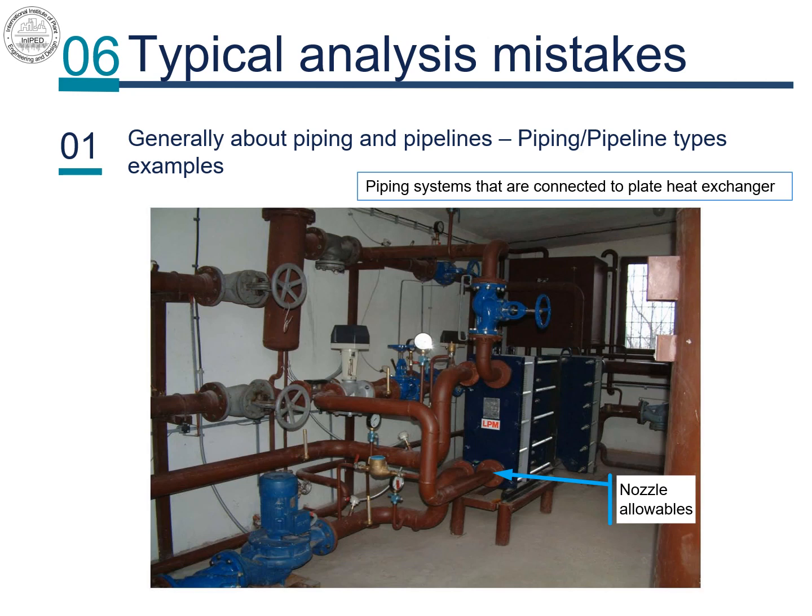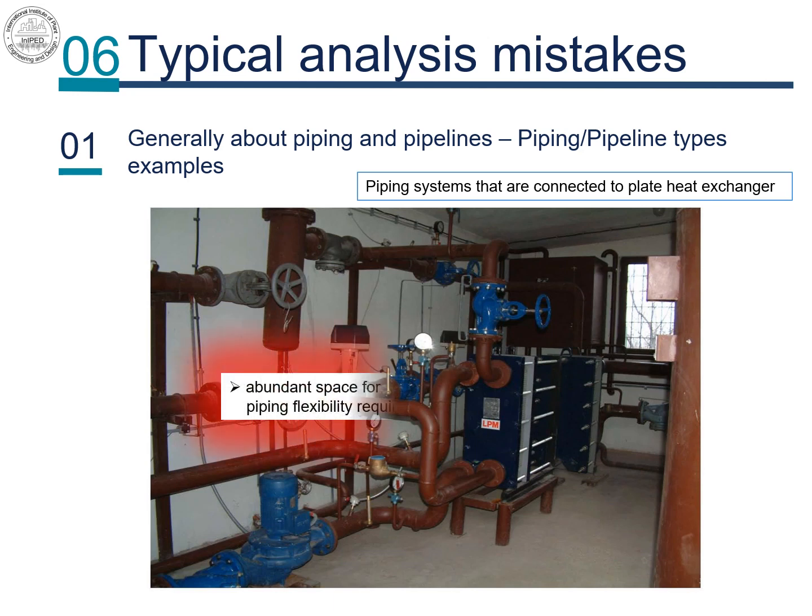in piping design. However, if we decide to count on the benefits of compactness, we should not forget, on the other side, the need for provision of excessive piping flexibility. Hence, unless a feasibility study is conducted prior to deciding to go the plate heat exchangers route, the rushed, overall conclusion about benefits that was assumed above might be overrated, and should not be generalized.